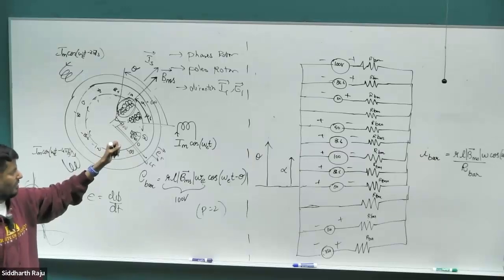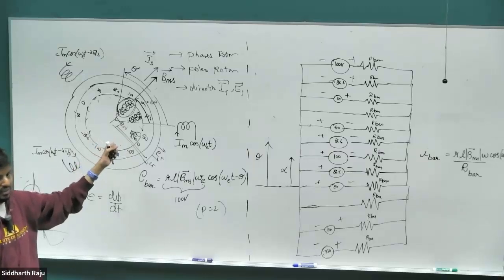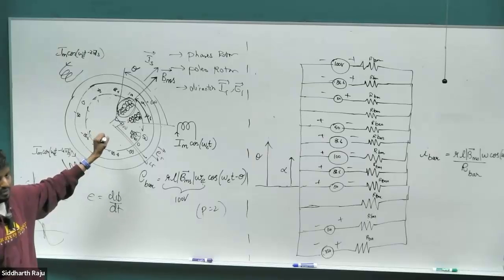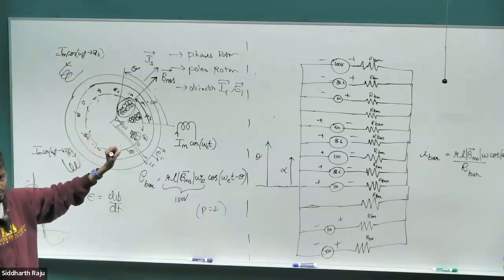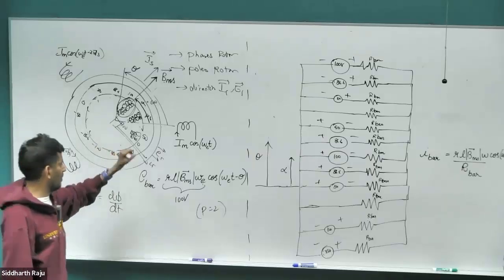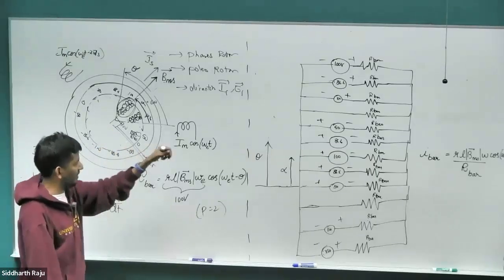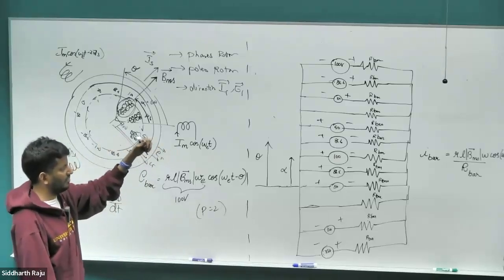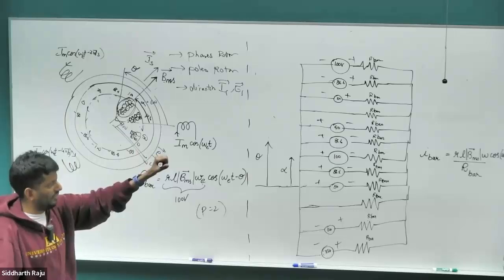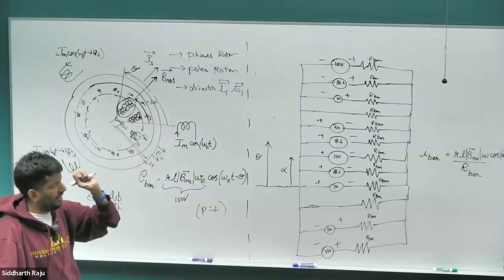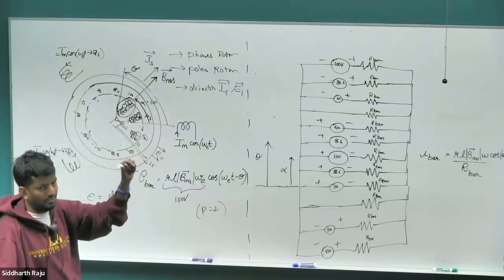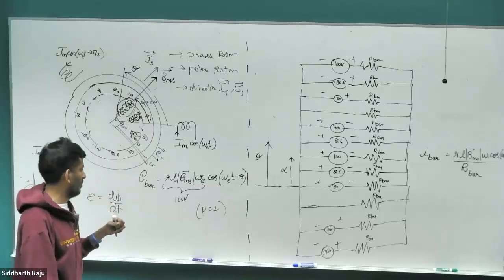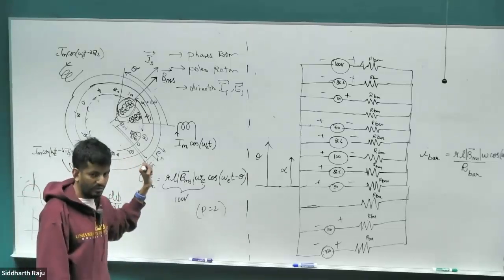And we made an observation that phasors and space vectors end up being the same. If you were to freeze time at one particular instant and look at the space vector plot, it ends up being the same as the phasor plot. Right? So when we look at the phasor plot, we have this orientation, perfectly aligned with what we had before, and it also aligns with the physical interpretation that we have for the current space vector, being that it's somewhat measuring the current density distribution and giving a surface direction to it, and the point where it's pointing is where we want the current space vector to be. Right? Everybody clear on this aspect?